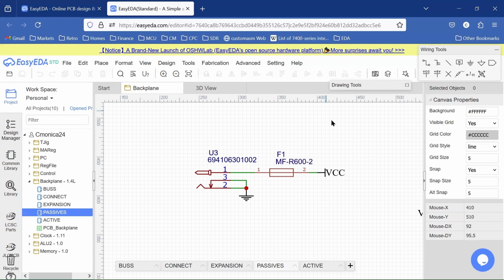Until the capacitors charge, and then the current comes down. That peak, that current surge to charge the capacitors and charge the circuits, is called inrush current. And that current spike can be very high and could be very damaging, again, to components or even worse, traces in our circuit.